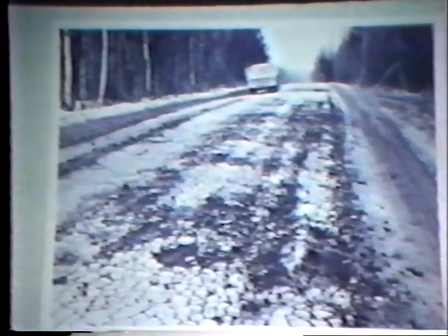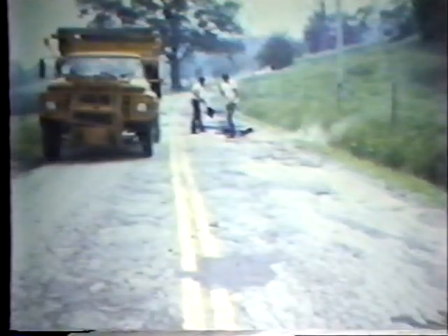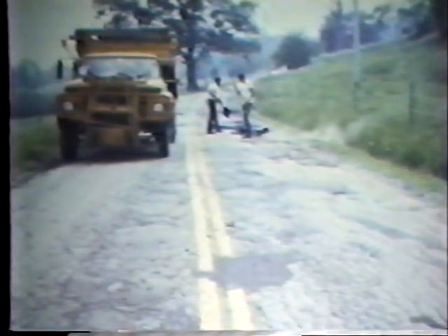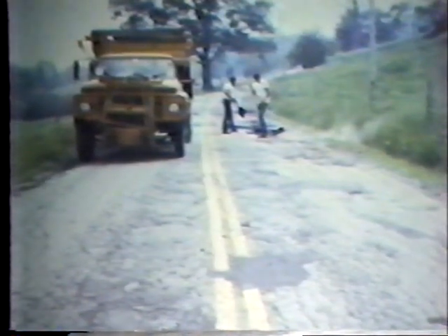And the reason is we're trying to prevent this, because that's what's down the road if we don't do something to seal the roads. With or without bad drainage, if you don't do something, this is what you're eventually facing after a bad winter. Or, much worse, something we call, my favorite slide, too little, too late, and you're really facing something that you probably should think about heavy overlay or recycling altogether. Just go in and rebuild it, because there's too much work to prepare it for sealing.